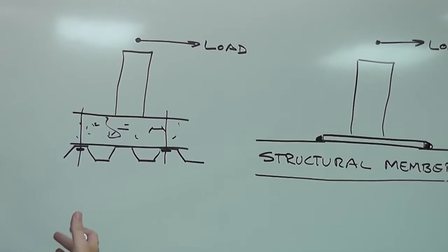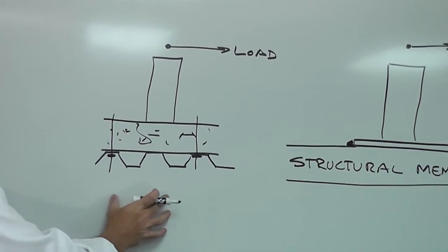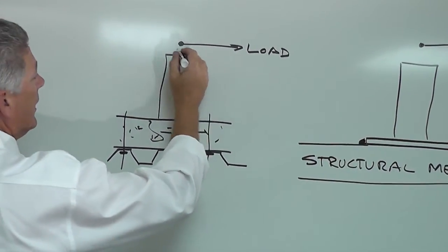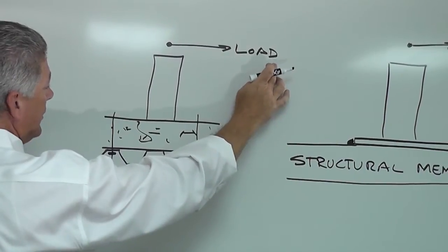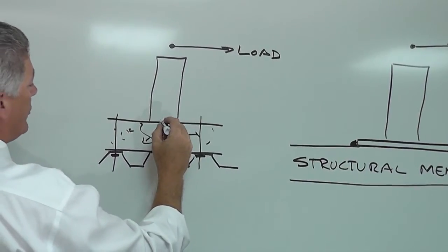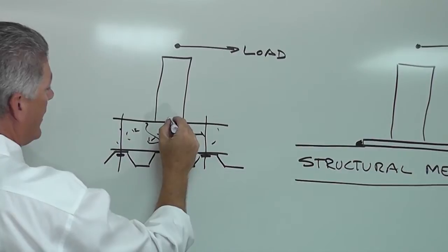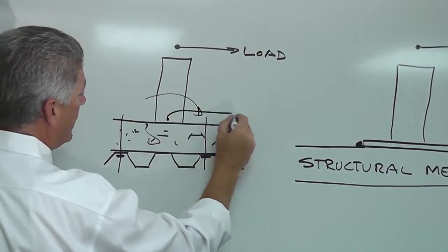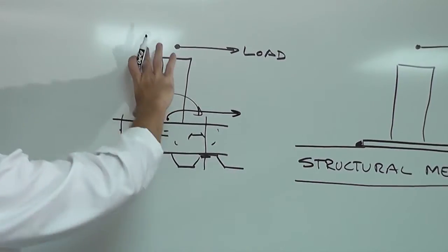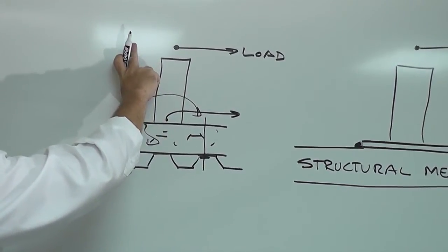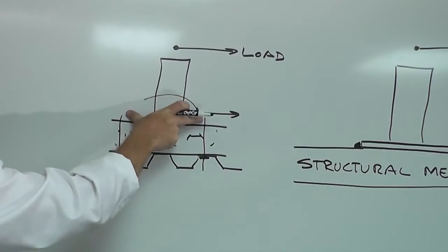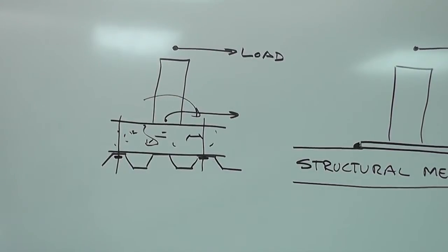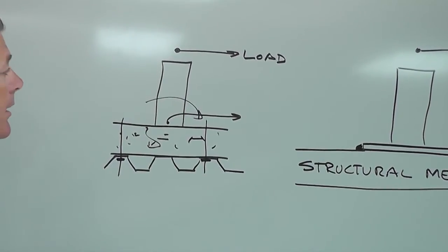In a load reaction on a tip-over post, the load goes off in this direction and would actually take this post, and the post itself around the connection point here would rotate, and now your load would be down here. So normally, if you were up at 12 inches at this point, it will rotate down and put this entire connection into a shear orientation.